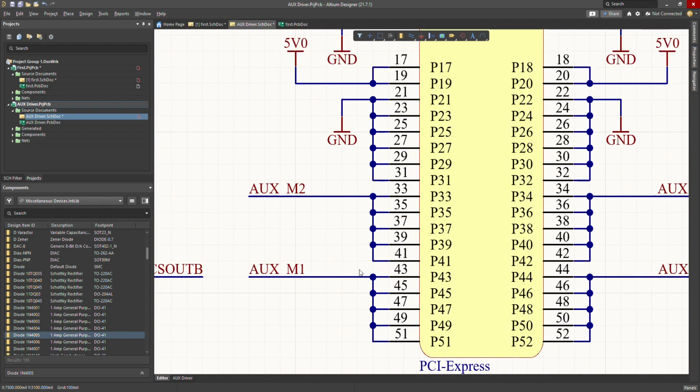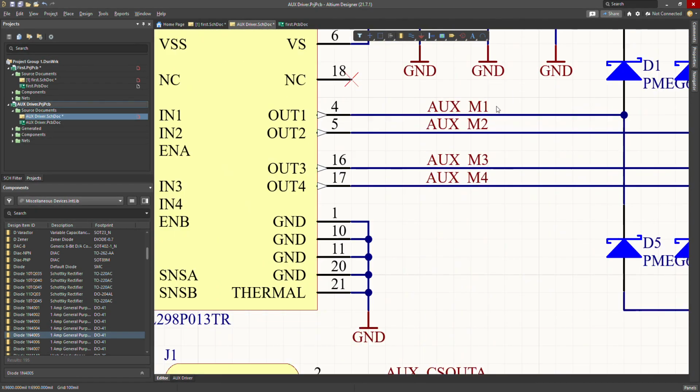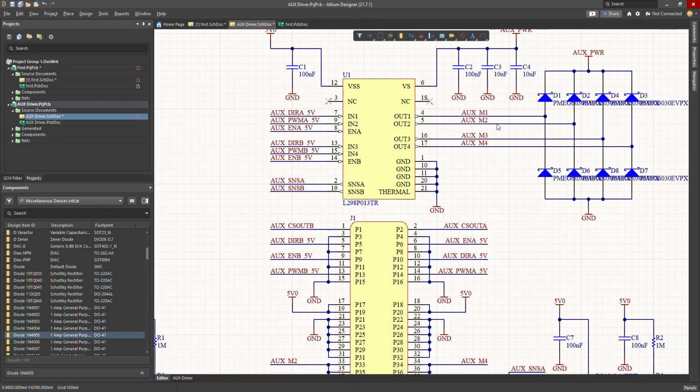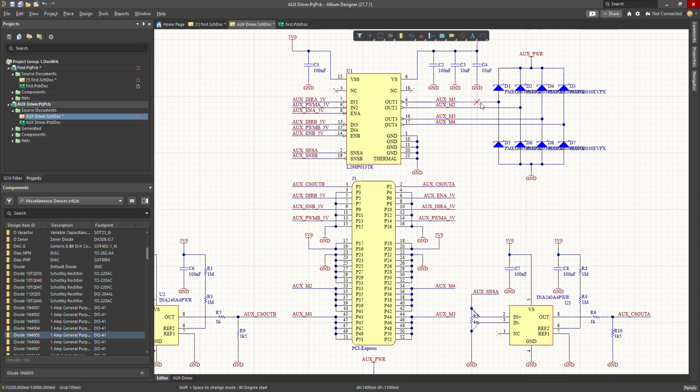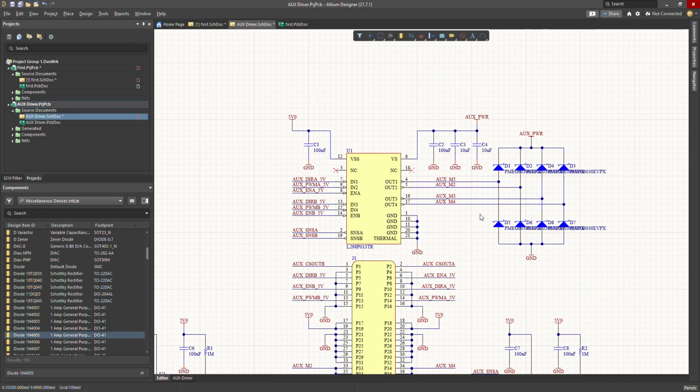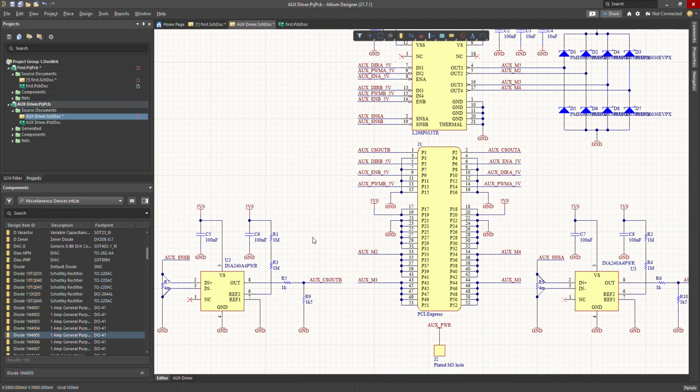Now this group of wires here and these wires here, all of them are connected to this wire here because they have the exact same name. That's how we connect components, as I mentioned, that are really far, and we don't want to draw a big wire from here to here to here. That is not ideal.